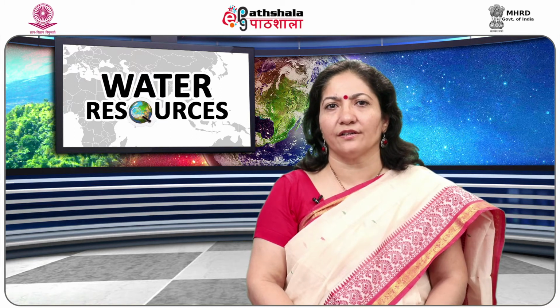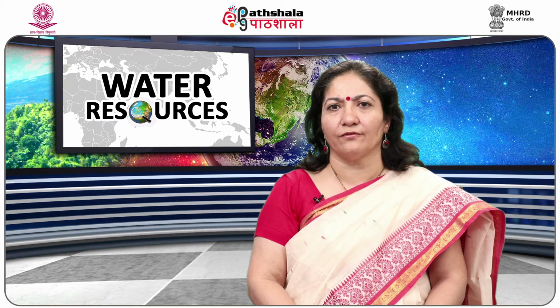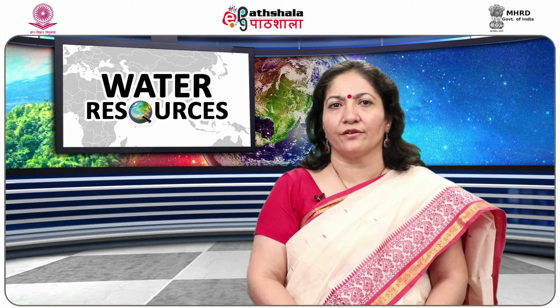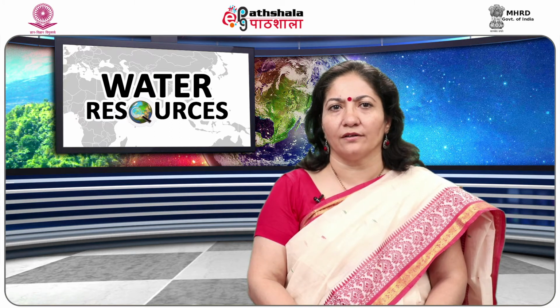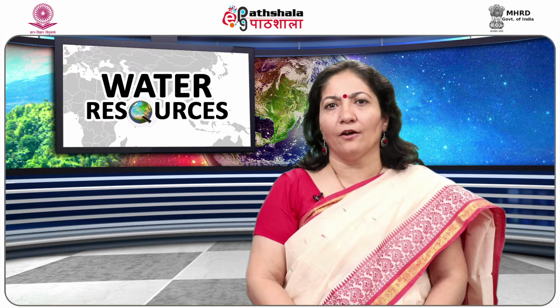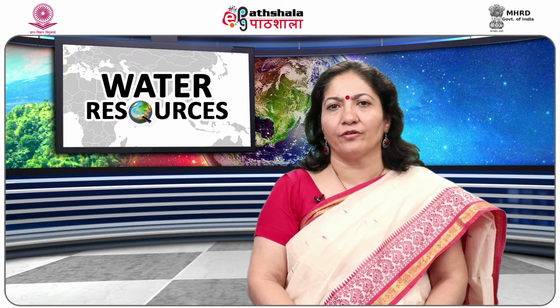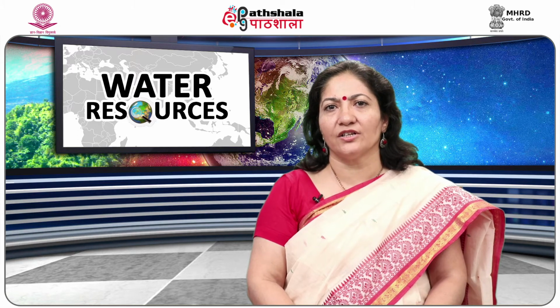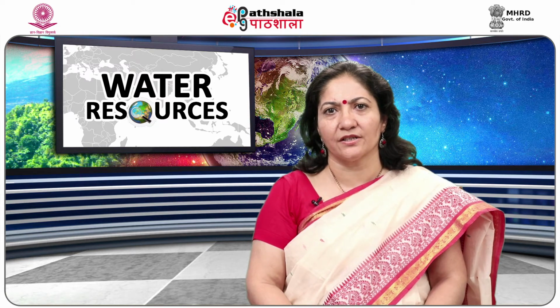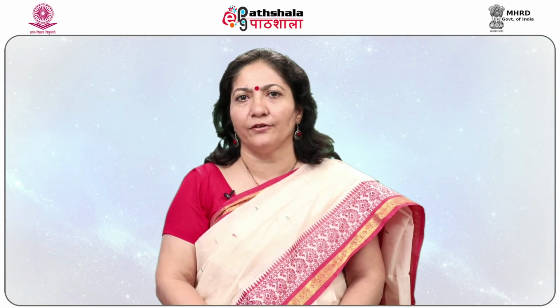Well-rounded coarse-grained sediments usually have higher porosity than fine-grained sediments because the grains don't fit together well. You can see the fourth figure. Very fine-grained rocks make poor aquifers because of the surface tension which holds the water in them. Some shales can have up to 90% of the open space, which is depicted in figure number 5. Figure 4 shows the well sorted unconsolidated sedimentary, and figure 5 shows the poorly sorted sedimentary.